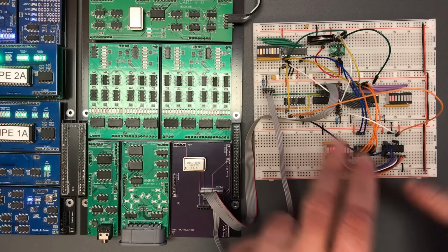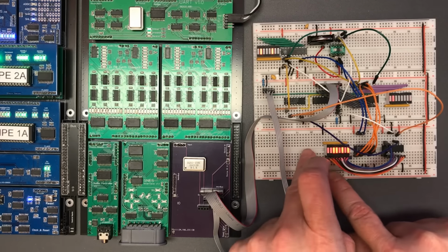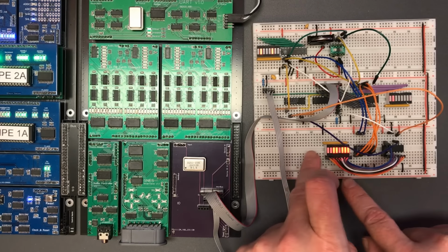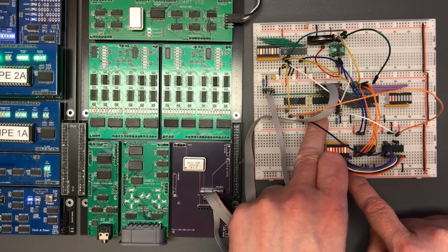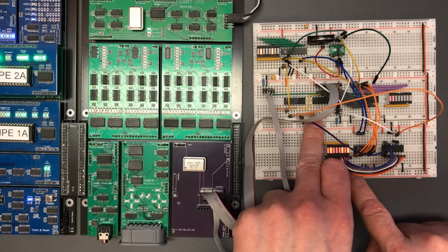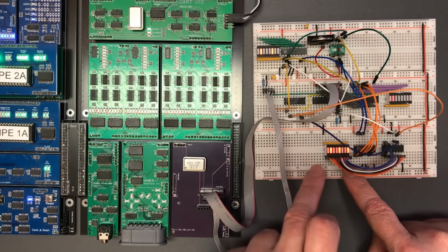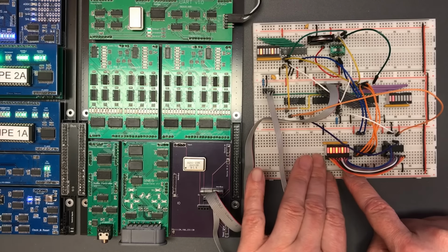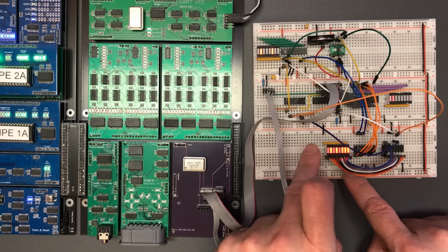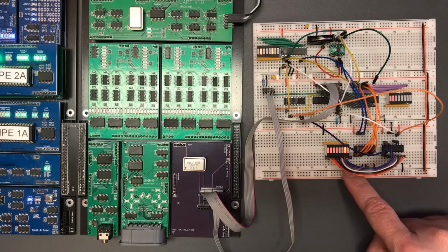Of course, we haven't actually changed any of the fundamental working of the code or circuit. We've just kind of got a shadow copy of the data read in. But if we replace the data that we output to the bus when we read with this, we can avoid all those individual 1-bit reads and all the shifting in the code. And I think that's going to be a significant improvement for us. But let's take a quick look at this on the oscilloscope before we start making that change, because I want to be able to make some before and after comparisons.